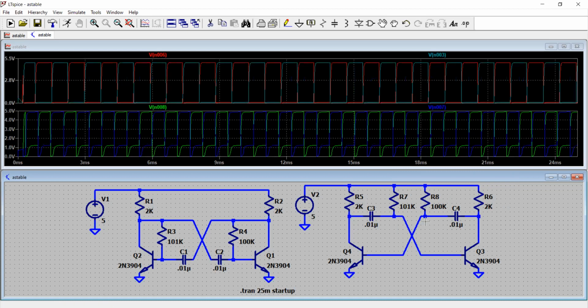So the second part of the circuit looks better, and that's how you can see the modification of it. So go for the second side of the circuit. Again, if you want to play around with changing the time period and therefore the frequency of the waveform, just play with the capacitors.